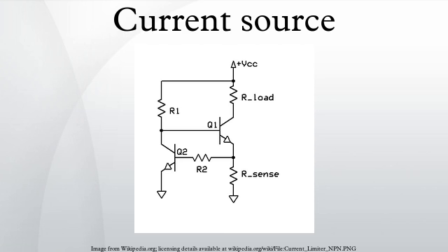For a nearly ideal current source, the value of the resistor should be very large, but this implies that, for a specified current, the voltage source must be very large. Thus, efficiency is low and it is usually impractical to construct a good current source this way. Nonetheless, it is often the case that such a circuit will provide adequate performance when the specified current and load resistance are small. For example, a 5 V voltage source in series with a 4.7 kΩ resistor will provide an approximately constant current of 1 mA to a load resistance in the range of 50 to 450 ohm.